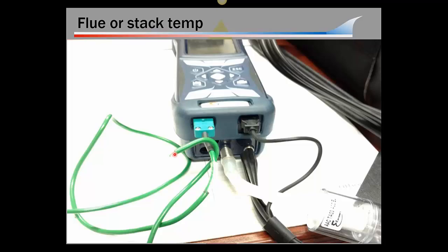You drill an 1/8 of an inch hole in the combustion air intake and put this in, because the machine, in order to do accurate math about efficiencies and stuff, has to have accurate input. It needs to know, what is my intake air temperature? If my furnace is pulling its intake air from the outside, and the outside is dramatically different in temperature than the inside, I need to get that reading so I get accurate numbers. Now, let's say that the inside is 70 and the outside is 65. Okay, I'm fine. You don't need to put that in. There's only a 5-degree temperature difference, and it's been my experience that's not going to cause a big change.